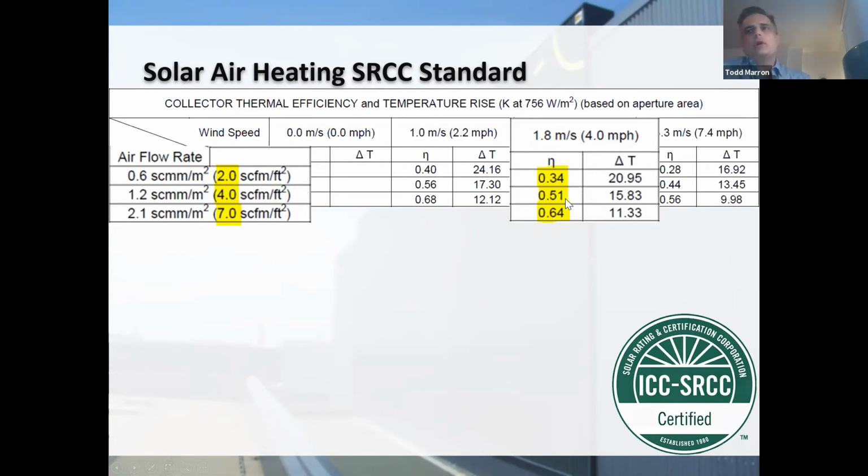So you take the solar energy landing on that vertical plane, keeping in mind that we're on a 90-degree angle, right? Which, if that was PV panels, that would be no good, because all July, all August, all June, you wouldn't get the sun because it's so high up. But keep in mind that for a solar wall system, we don't care about summer. We only want the winter production, because during summer, you're not heating your building. So on the vertical, you actually get really good production in the winter months, much, much better than, say, a 30-degree angle of a PV panel.